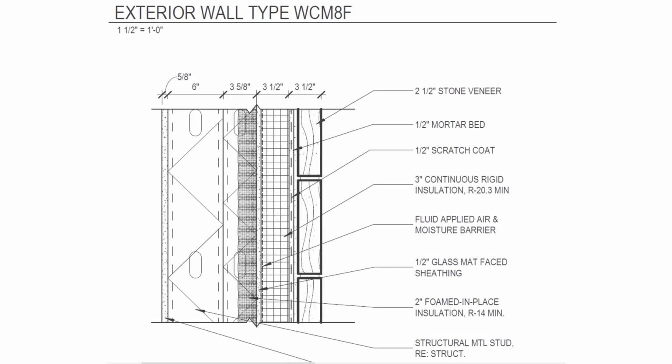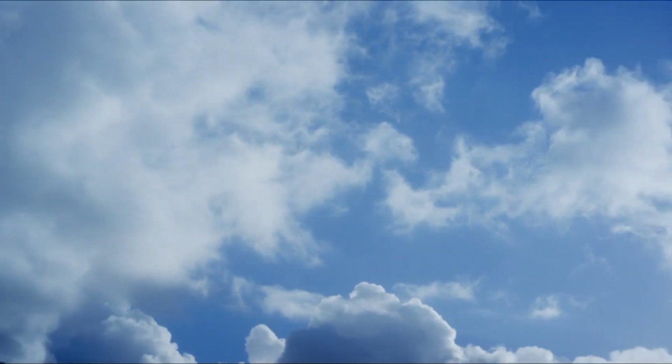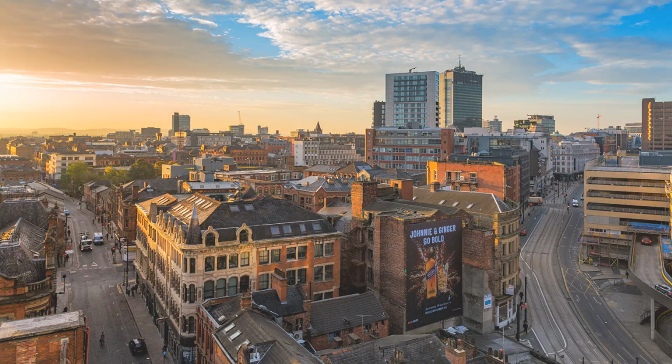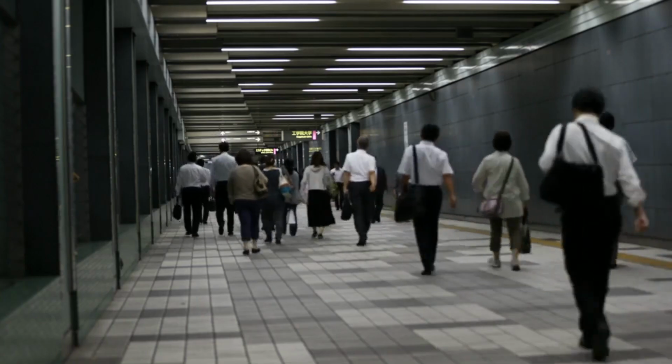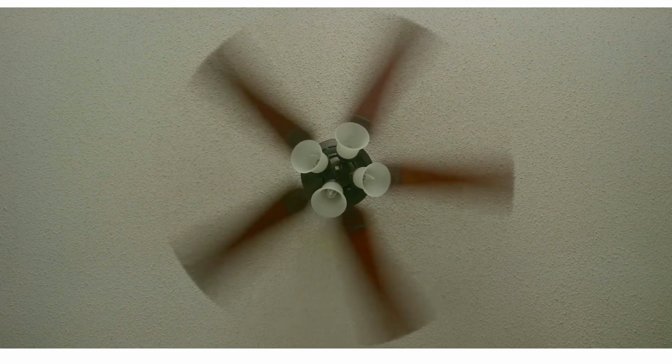The first step is to determine these heat gains and losses in the building. To do this, the team uses the provided ASHRAE architecture drawings of the building that includes construction materials and construction envelope. Building off of these, the team creates models in Carrier's proprietary hourly analysis program, or HAP. HAP makes use of the building architecture, local weather data, building location, as well as applied data inputs such as heat gains through intended occupancy of the building and heat gained from lighting and other electrical equipment within the building